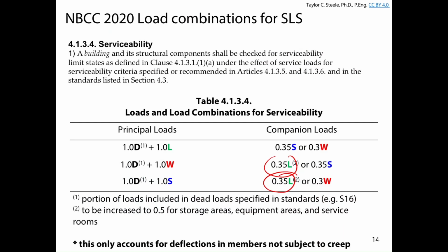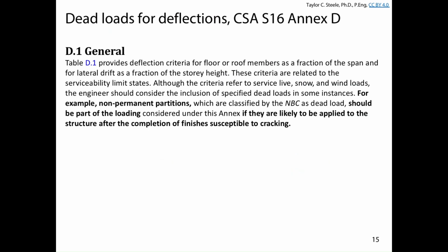And so all that deflection is just sitting there, right? The deflection is what it is under the dead loads at the time that you're installing the floor. And so it doesn't really matter what that deflection is. I don't care as a steel designer, well, I do sometimes, but not in this course. I don't care how much deflection is already there. I just care how much deflection is going to come after the floor is installed, right? So sometimes we won't include any dead load at all in deflection calculations because it's already all there. But sometimes if the partitions are temporary and they can be moved, then we'll just include the partition weight in our deflection calculations.